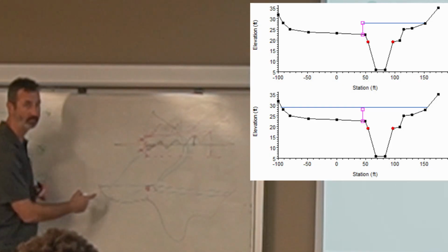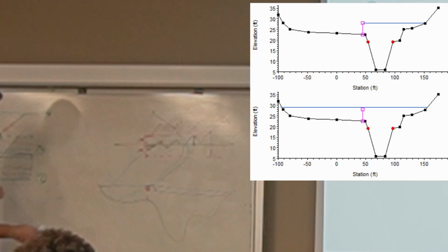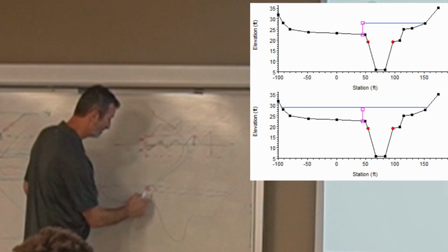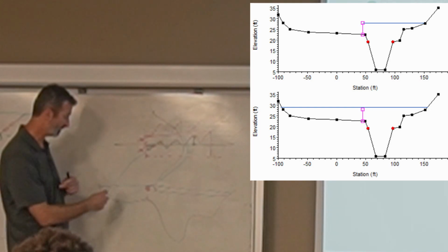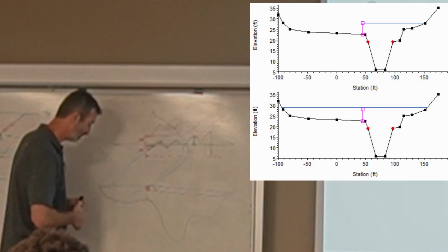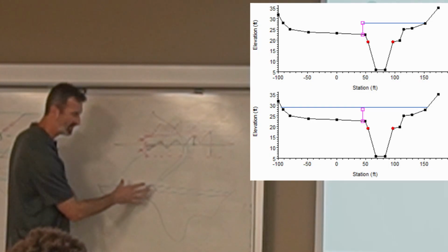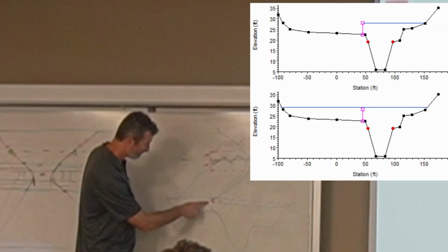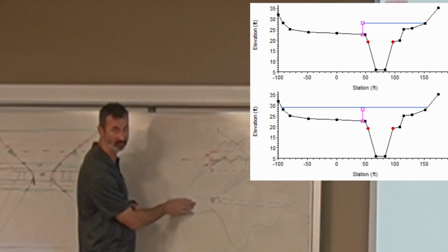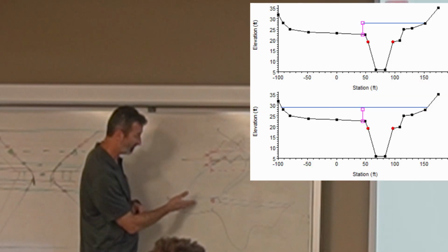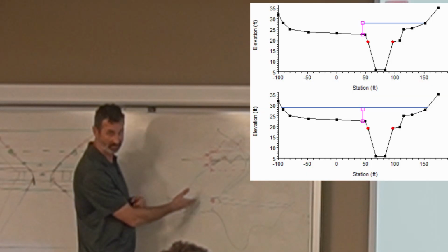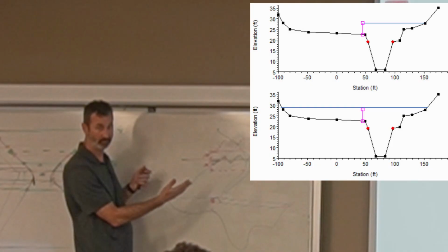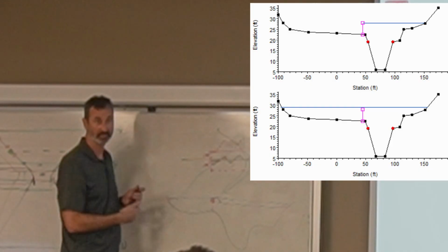And then this one is way too high, because there's all this other area out there, and a lot more conveyance is happening. So it can be hard to balance, and it might not even be immediately clear what the right answer is. You need to decide what is going to happen over here if that does actually get topped. Maybe full flow is the right thing? Full on, all the conveyance over here is actively conveying downstream.